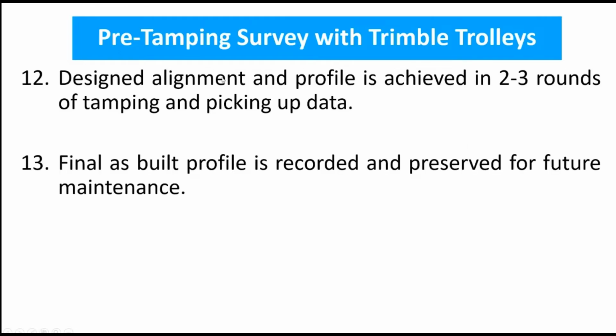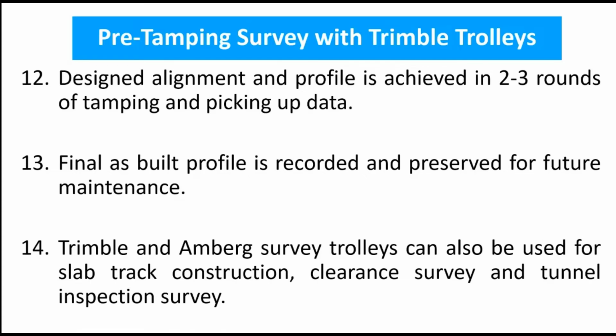Finally, after reaching the design alignment, the final as-built profile is recorded and preserved for future maintenance reference. These survey trolleys basically have a total station, prism and software.